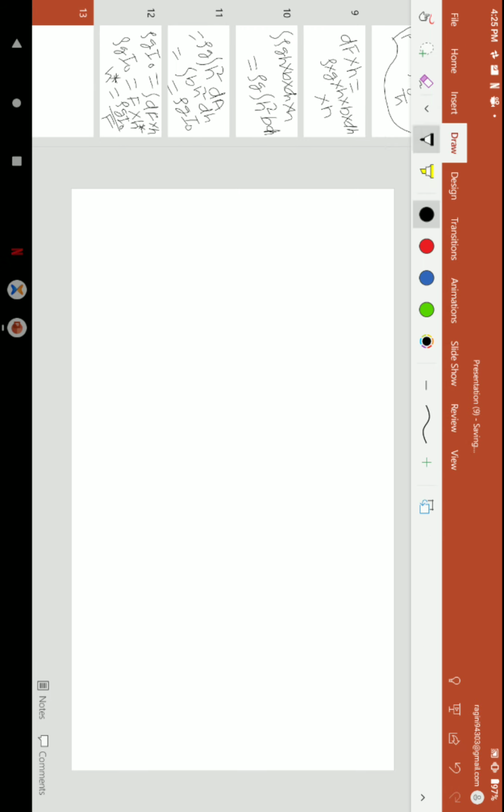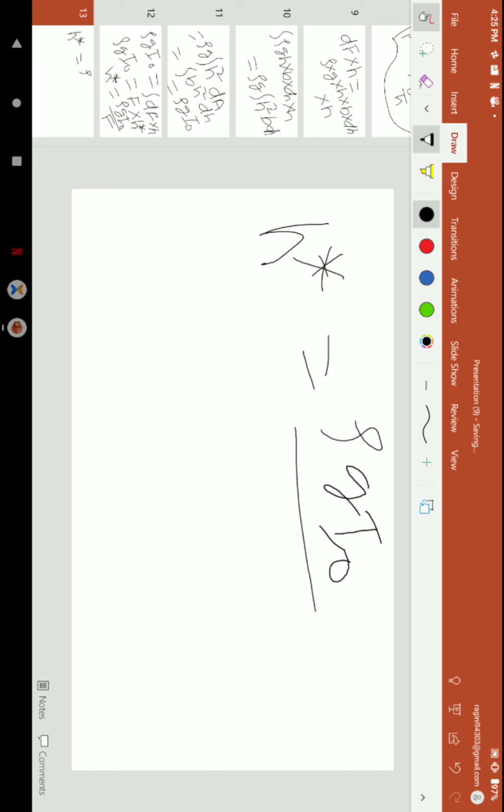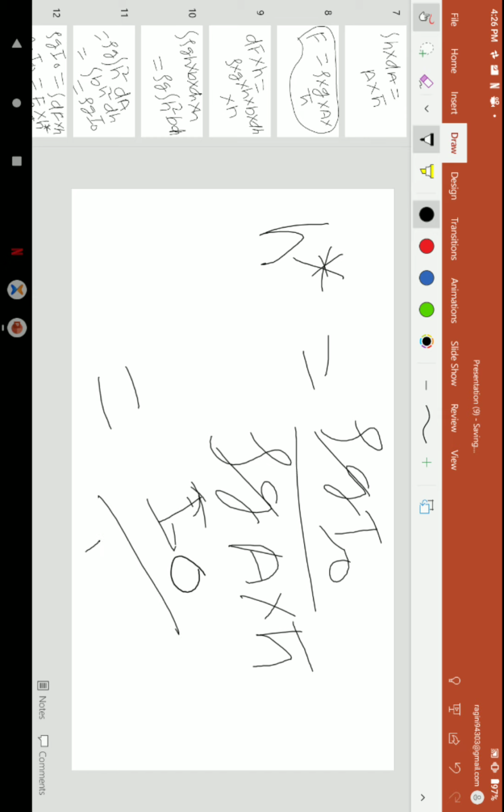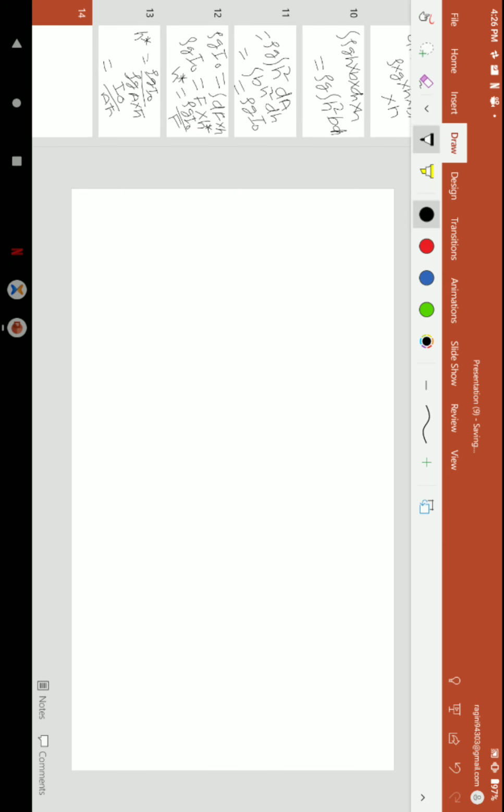Let us see. Again, h star is equal to rho g I naught divided by f. What is f? F is rho g a into h bar. The rho g and rho g cancel. What is left now? I naught divided by a h bar.